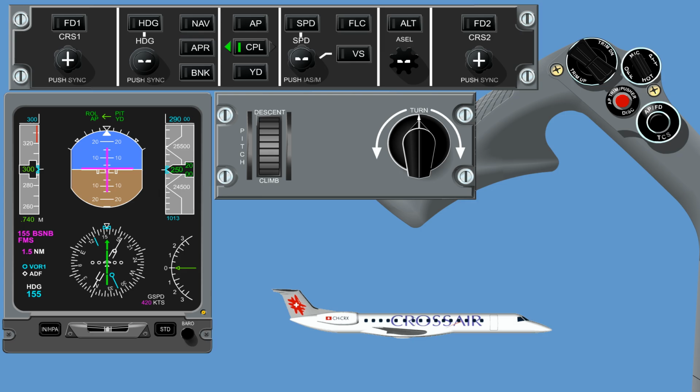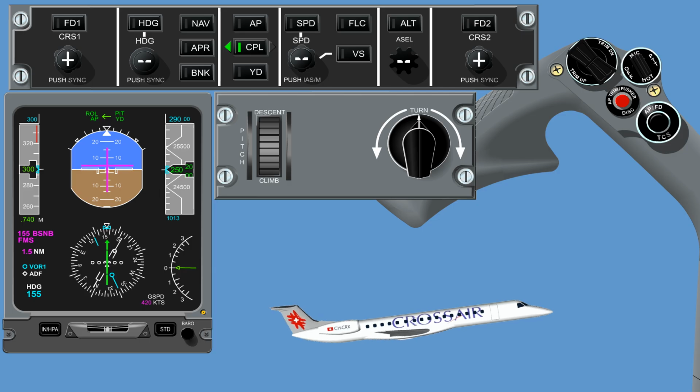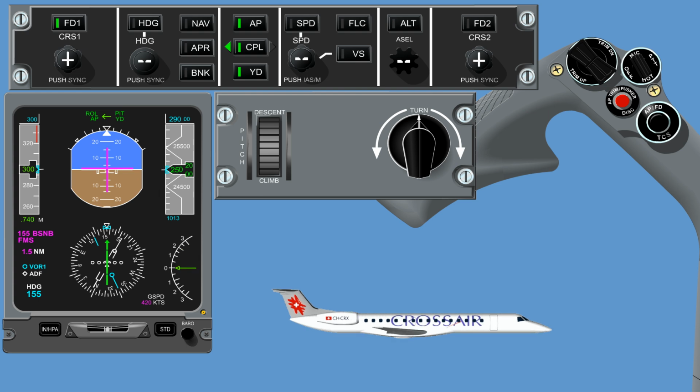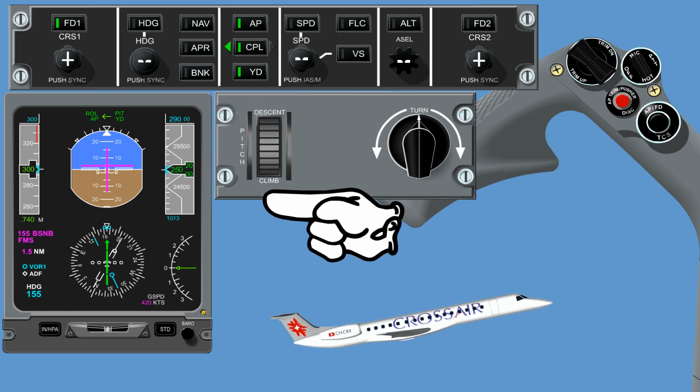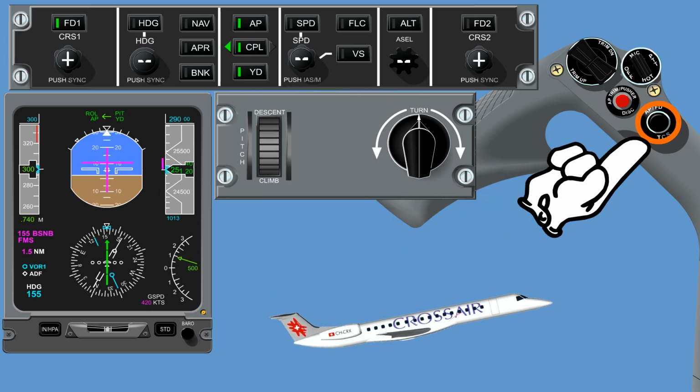The Autoflight system will operate in different vertical navigation modes. The pitch hold mode is the vertical default mode and is enabled when no other lateral mode is selected and the autopilot is engaged. If these conditions are satisfied, the airplane will maintain the pitch attitude and a pitch annunciation will be displayed on the primary flight display. The aircraft pitch angle can be changed either by turning the pitch wheel or by pushing the touch control steering button on the control wheel.